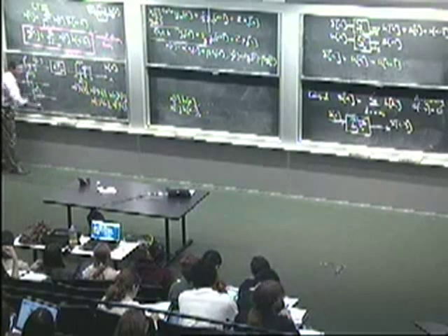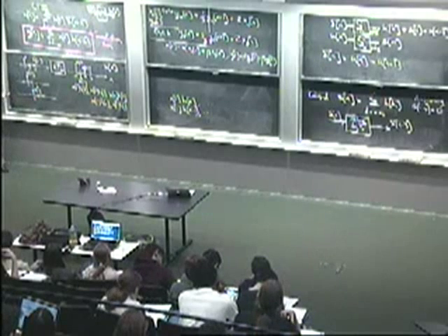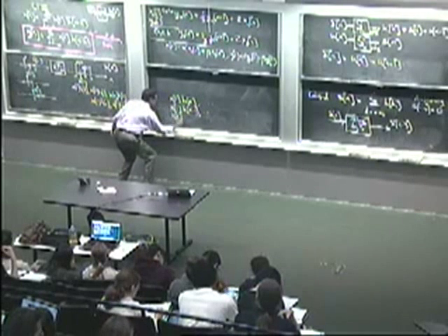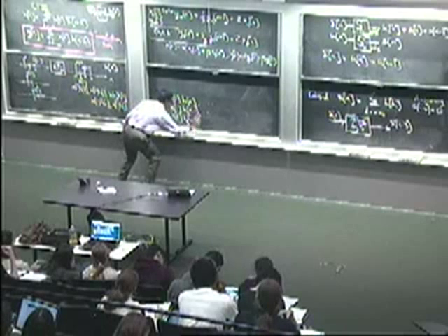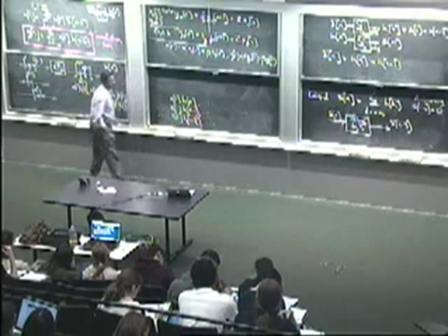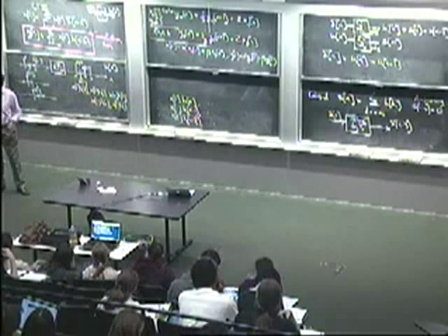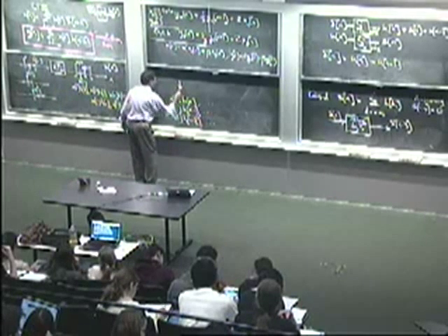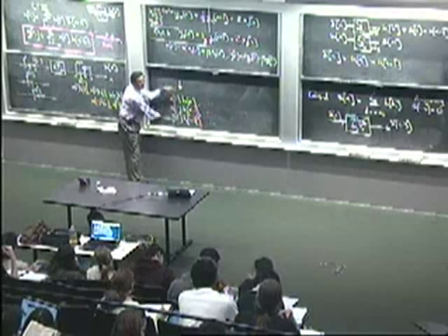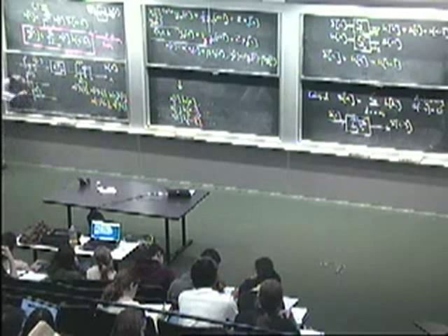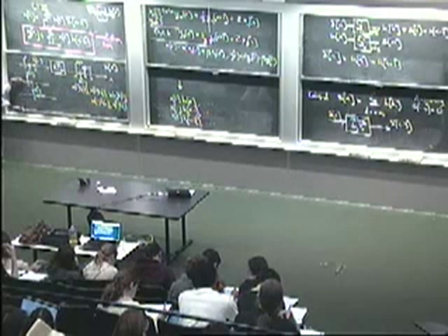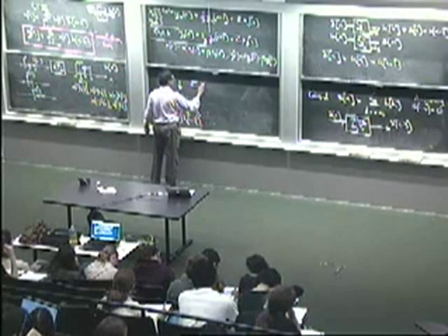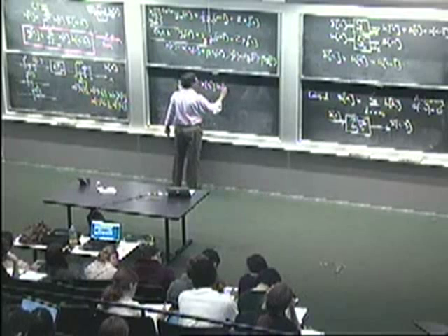Each one of these will fire off a scaled unit sample response, but delayed appropriately. And so at the next time, what you're going to get here is x[2] h[n-2], and it keeps going. And what if you're interested in the value at time n? Okay, so you look along here, and you've come to the value at time n. So it's going to be the sum of all of these if your input is the sum of all of these x's, right? Your response is going to be the sum of all of these. So what's the sum of all of these? Well, x[k] h[n-k].